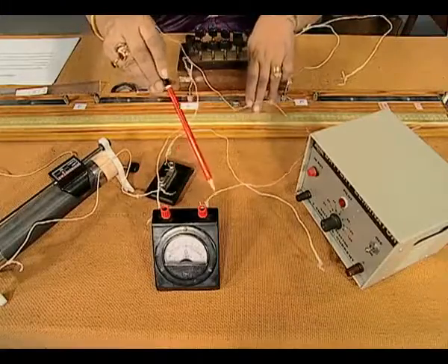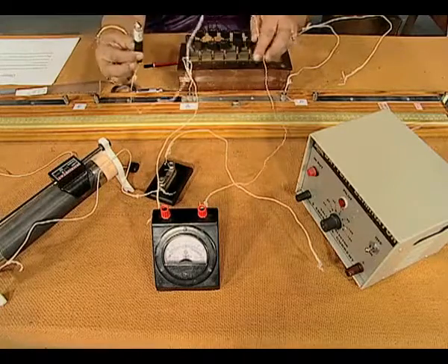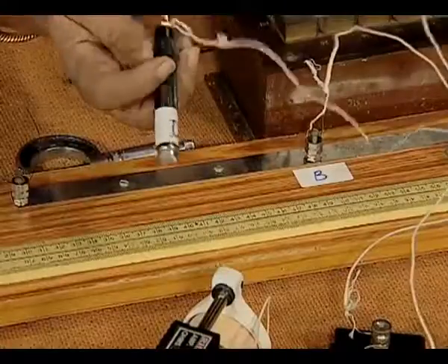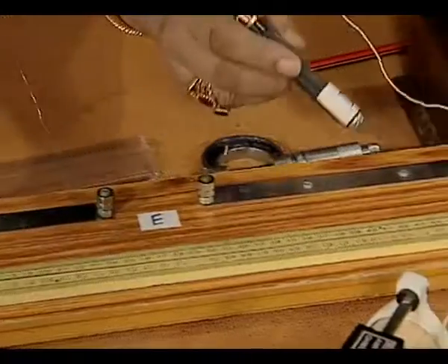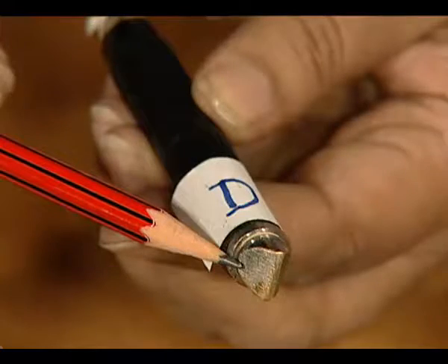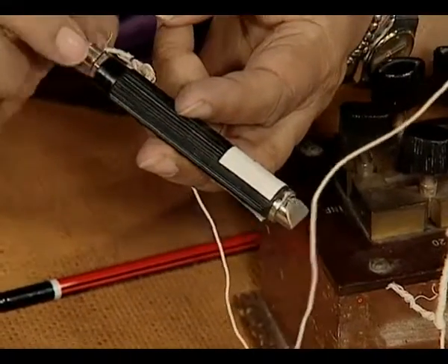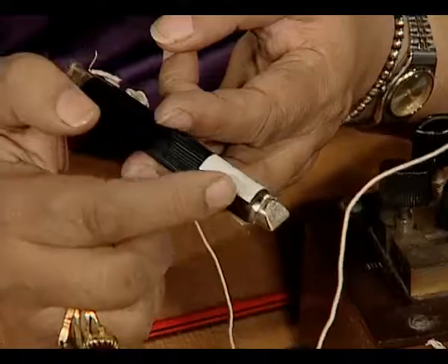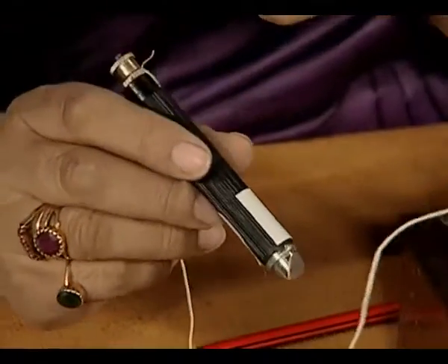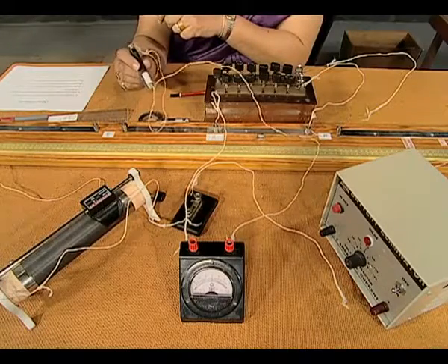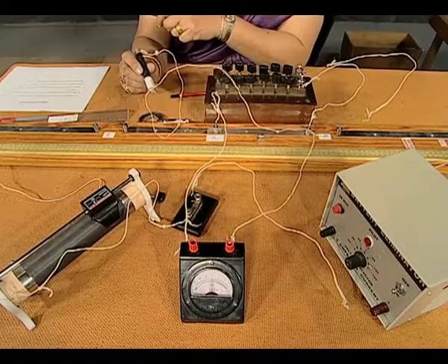The galvanometer second end is joined to this jockey. The jockey is this flexible point which can be taken anywhere on the wire. It is designed to have an edge on one side. There is a metallic rod between this terminal and this end, so that the connection is there. This portion which we touch or hold the jockey with is made out of ebonite or plastic. So, we do not touch the wire.